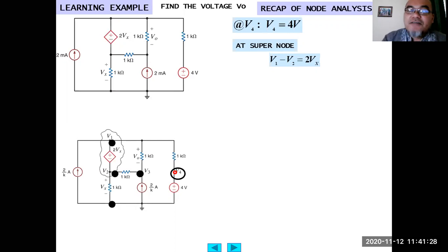Because in quiz 3 as well, to solve number 3, some of you redrew the circuit and made the reference node some node which does not have the most branches. Yes, you can still solve it that way, but you just make your life more difficult. That is just a rule of thumb: choose the node with the largest number of branches as the reference node.